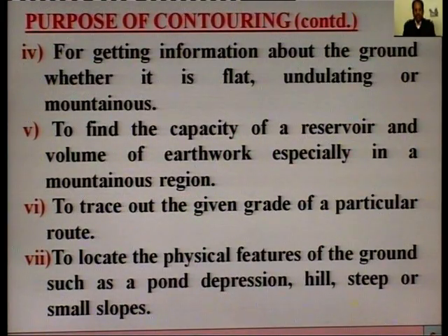Next is to trace out the given grade of a particular route, that is, on a hillside. If we are to select an alignment of a road, we will have a number of options and we can select the best suited alignment by doing contouring.